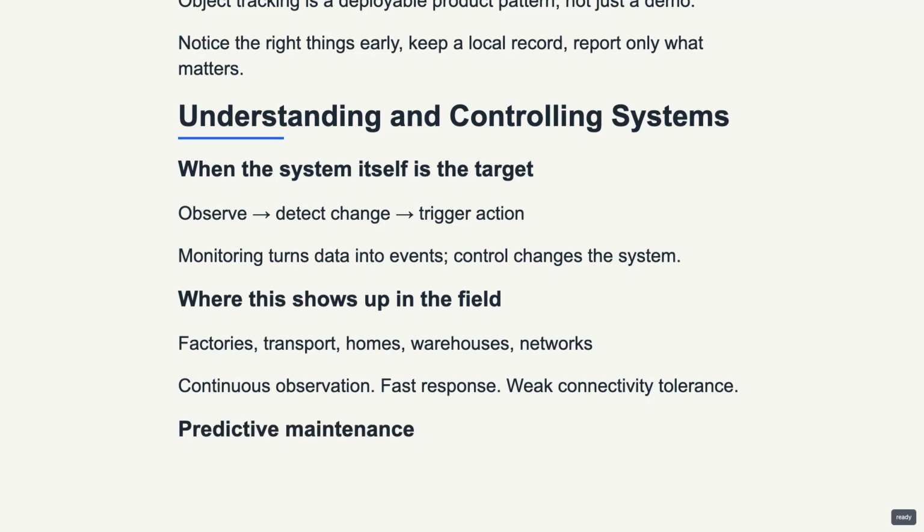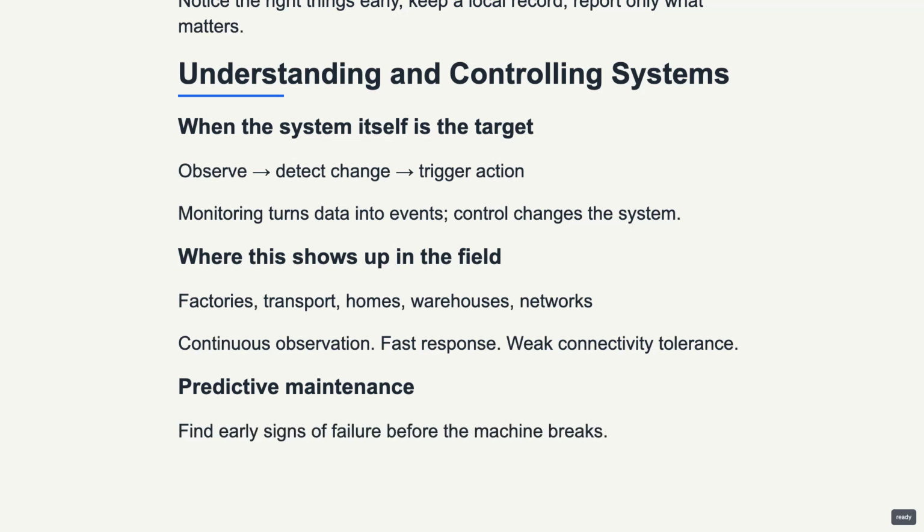Predictive maintenance gives the cleanest example of this idea because the value is easy to see. Catch failure early enough to prevent downtime and damage. The model is looking for weak signals hidden in noisy sensor data, like small changes in vibration, temperature, sound, or power use. Those shifts may look minor on their own, but together they can show that a part is drifting toward failure.